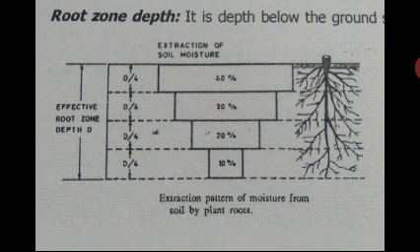The permanent wilting points differ widely for different soils, but have approximately the same values for different plants grown on the same soil. The value of permanent wilting percentage may be as low as 2% for light sandy soils, and it may be as high as 30% for heavy clay soils.